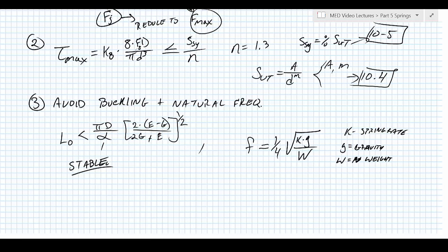They can do that. So now the natural frequency is generally not something that we get close to too many times. However, we can figure out this frequency is the first harmonic. The second harmonic will be the multiple of that. So it'll fail the first time we get to the first one. So as long as we don't ever get to the first one, we'll never get to any of the higher ones because it won't be going any faster than that.